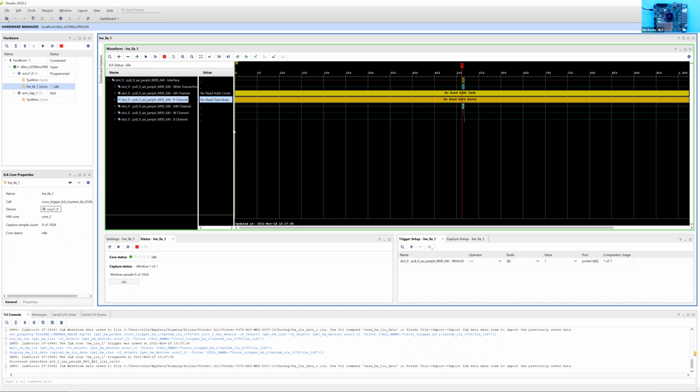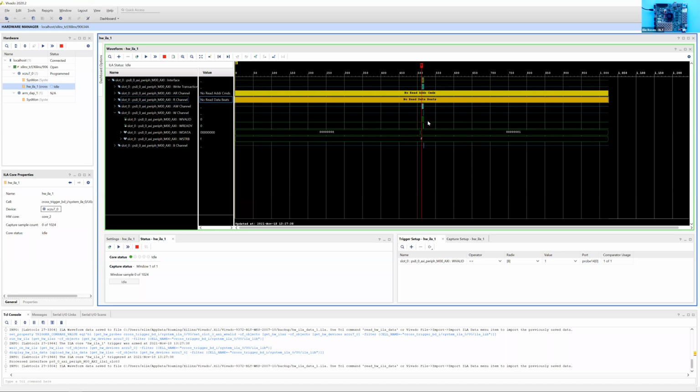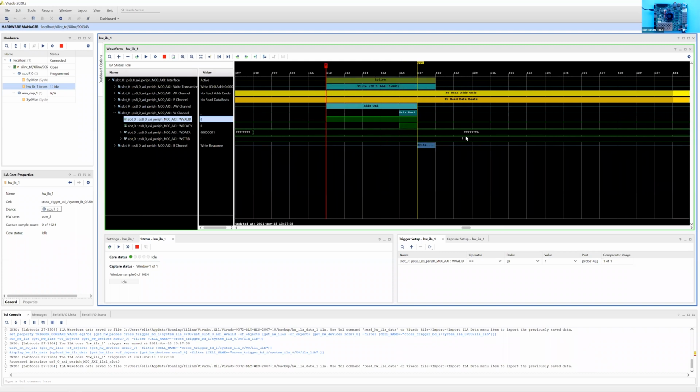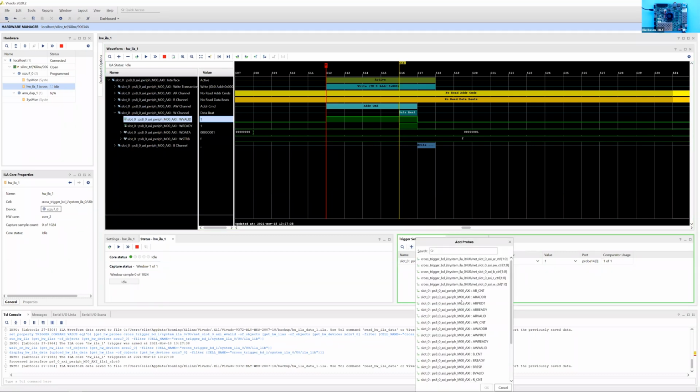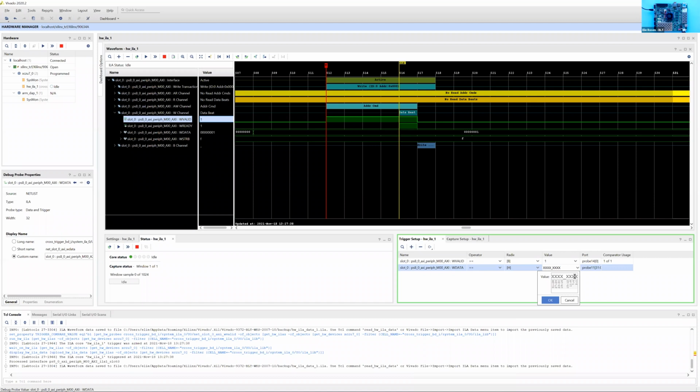And we caught it. If I look in the right channel, I can see that for this one clock period, we were the value 1, and I caught that data there on that one sample. All right. I also want to add here the right data. What if I want to trigger on, for example, the value A? So if I look at the data interface, I could say don't trigger until I see the value A.